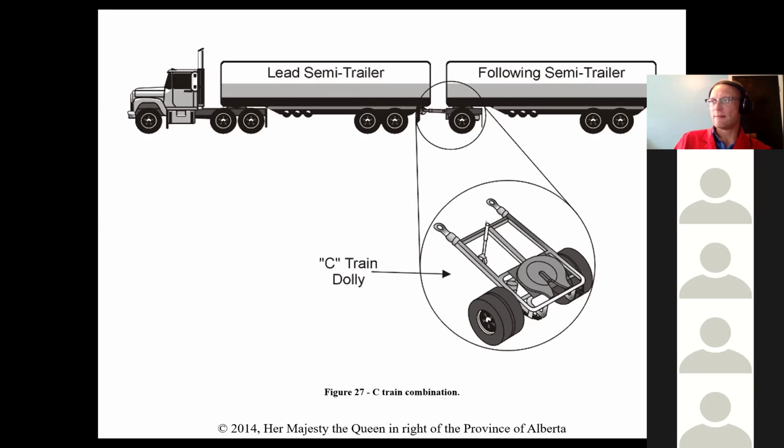So you should ideally be able to hook any tractor up to any semi-trailer, and I'm not saying it'll haul well and fuel efficiently, based on application, condition, all those things, but it should work. It should make the brakes work, release the brakes, apply the brakes. It should make the lights work, all of that stuff. A common combination I've seen is a body job gravel truck, like an end dump, pulling a flat deck with a backhoe on it.